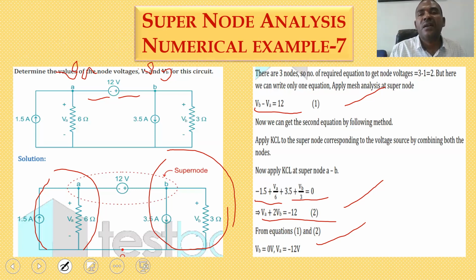At the same time, the main disadvantage of mesh analysis or nodal analysis is that the complexity of the network increases. So it is very difficult to do the calculation, and the time will be very long. At that time, you have to go for network topology or network reduction techniques, either star to delta transformation, source transformation, or series parallel combinations, or you can go for equivalent circuits such as Thevenin's and Norton's.